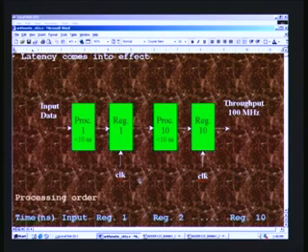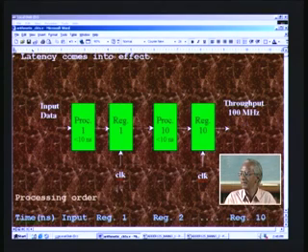Suppose the clock period is 10 nanoseconds; you need 100 nanoseconds of latency, at the end of which the output starts appearing. The advantage is that we can now have a 100 megahertz clock, because process 1, process 2, up to 10 all add up to 100 nanoseconds, as we started with in the traditional approach.